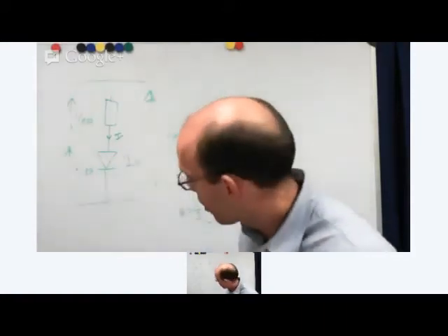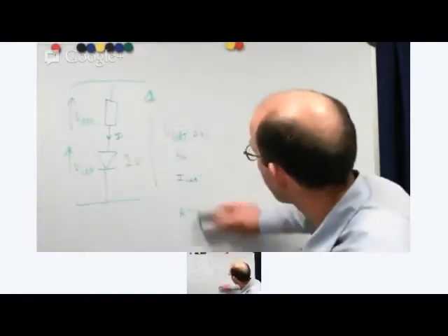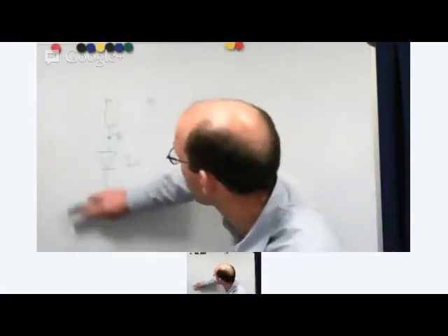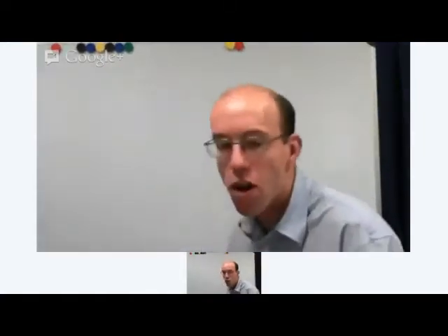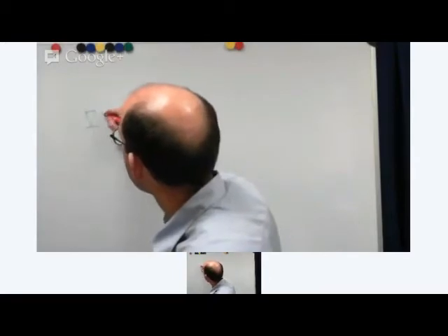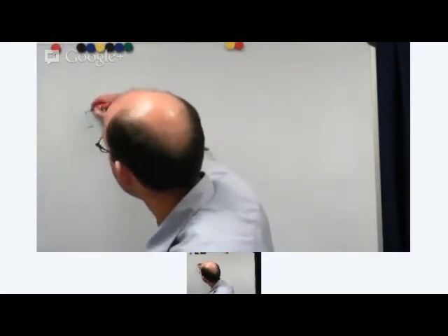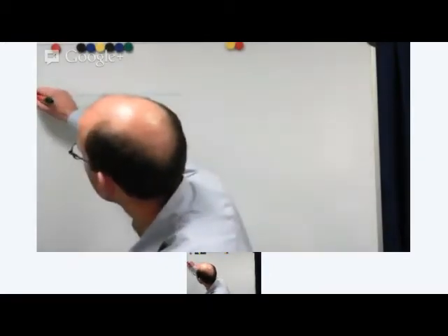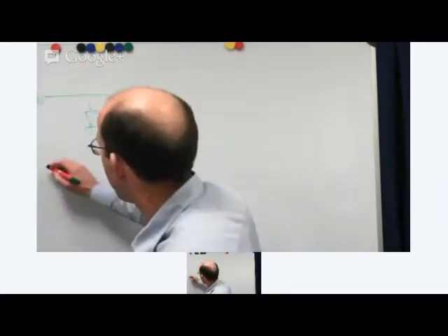One of the other questions that we get asked from time to time is to do with connecting multiple LEDs together, and there's various ways of doing this. I'm just going to start with the simple option. If we're doing colour changing LEDs, then we don't need a current limit resistor on a colour changing LED. So if we've got 5 volts here, and they'll work from about 2.5 volts up to just over 5 volts.